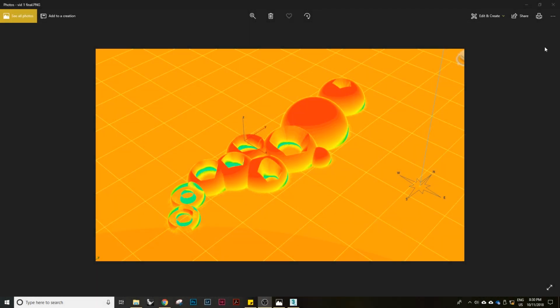Hi everyone. Today I'm going to show you guys how to use the pseudo color exposure control within 3D Studio Max. It's a lighting analysis tool that allows you to map these color gradients onto the surfaces of your geometry. It's used to analyze the different spots within the geometry where it's receiving more or less sunlight, as a way to inform a schematic design or the different perforations within this canopy structure.